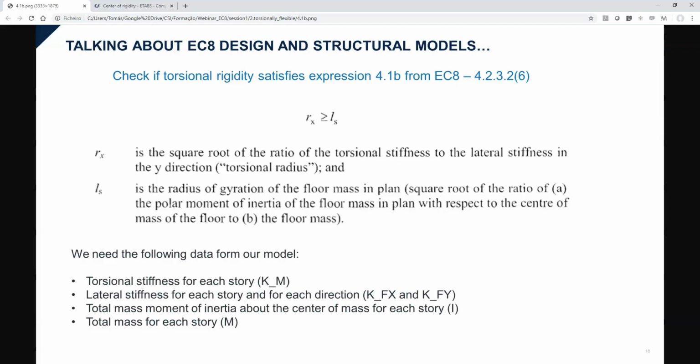This means we need to understand what bending stiffness and torsional stiffness mean at each story. It means that when a story is subjected to a force, whether translational or rotational, the relative displacements occurring between that story and the story below help us quantify the stiffness of that story, reflecting exactly the stiffness of the elements helping to resist. On the other hand, we cannot forget that these elements in each story are fixed into the elements of the previous floor. All these elements, perhaps at the first floor with total fixation, have a maximum stiffness. Therefore, torsional and bending stiffness vary across stories. Even if a building had all identical floors, the story stiffness would tend to decrease as the height increases.